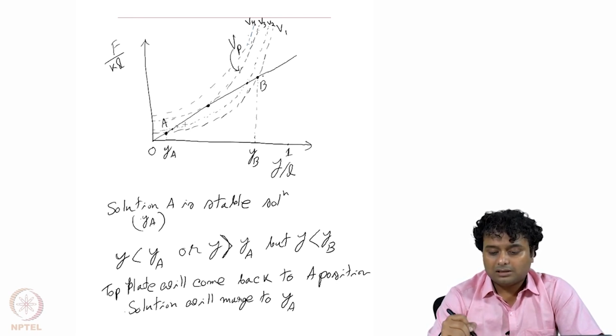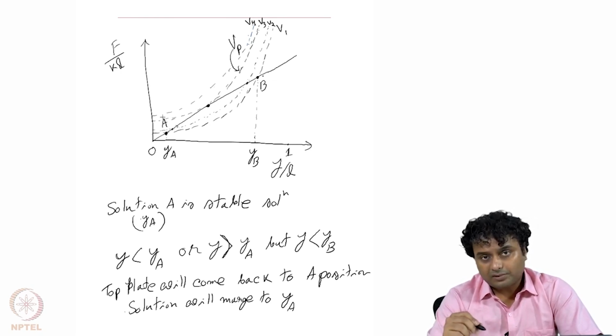So if I draw the resultant graph, it will be something like that. The resultant force will be the electrostatic minus the mechanical force. It will be initially positive, while y equals 0, then it will slowly decrease and cross over 0, and then go towards negative, because at this point the mechanical force is actually higher.